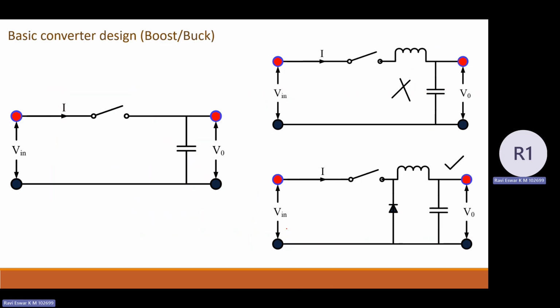So right now you can see here, the input voltage is here to this entire converter system. After the input voltage, the supply is connected in series with a switch. And then there is a diode, and then there is an inductor and a capacitor. This capacitor is connected across the load. So basically L and C try to maintain continuous current for the inductor, whereas continuous voltage for the capacitor, which is connected parallel with the load. So this converter, we call it a buck converter.